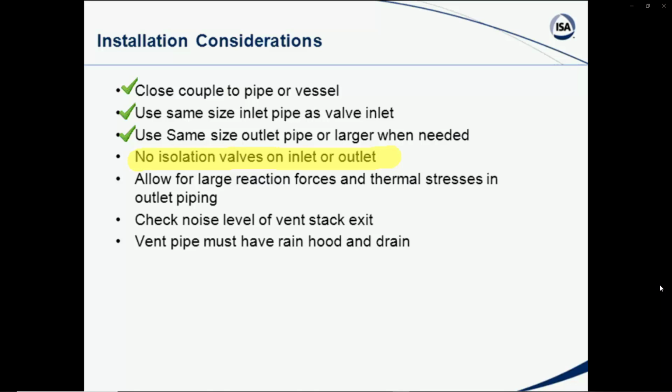If you arrange for a car seal or some sort of chain situation where you have to go through a process to close that shutoff valve off. Otherwise, you don't have an isolation valve on it without some sort of protecting system, okay? Also, you need to look out for reaction forces and thermal stresses. Vent pipe should have a rain hood and drain, and of course the noise level needs to be checked by the manufacturer. So that's some situation that should not occur on the exam, but I think we need to know about it anyway, so it's just a part of that.